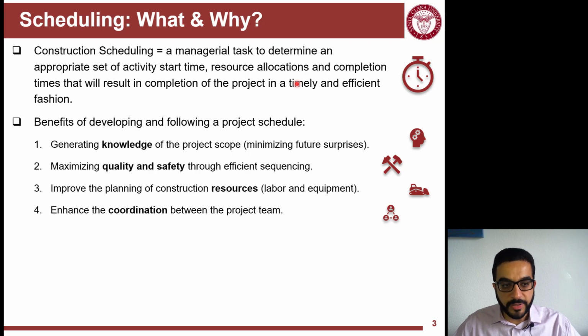And also it makes sense to lump and do together the activities that use the same resource. So if this crane is used for another activity, for example to install the roof trusses before, I will probably keep these activities in line or in sequence together in a way that this important heavy resource is utilized in the best way.